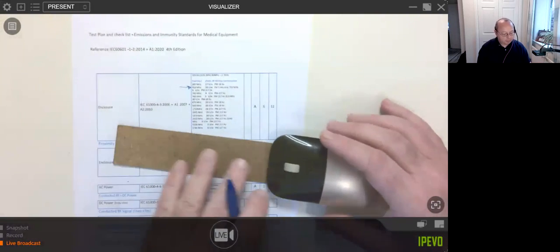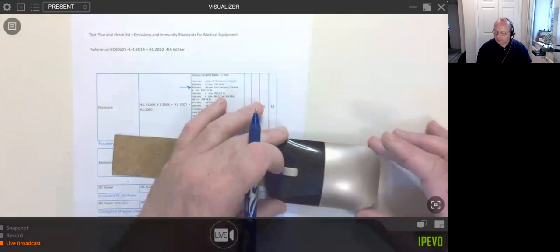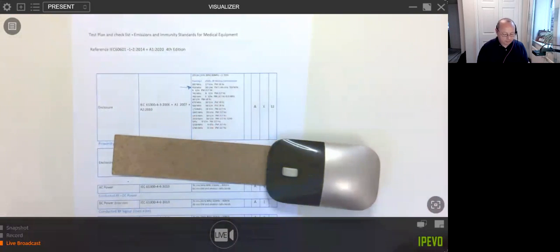So this is our board, represented by this mouse, that had a 4-layer board, brilliant. The problem was this Flexi Track had no ground in it. So it was just tracks, and the tracks were actually causing the ground voltage to drop, which then caused the temperature signal to drop, and it looked like we had a really screwed up reading.